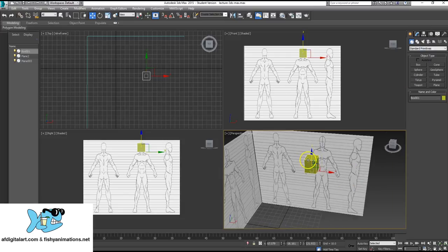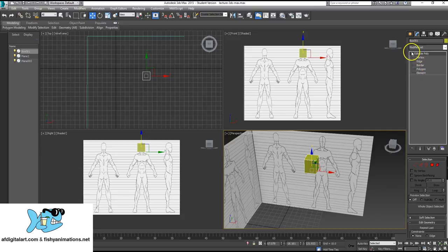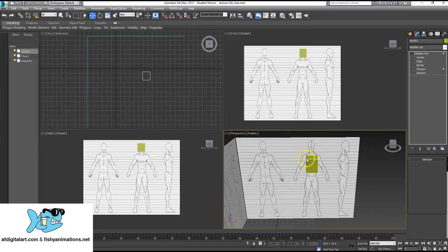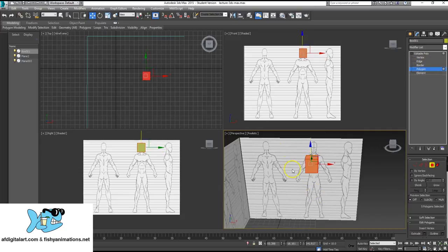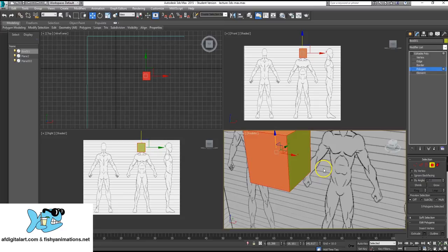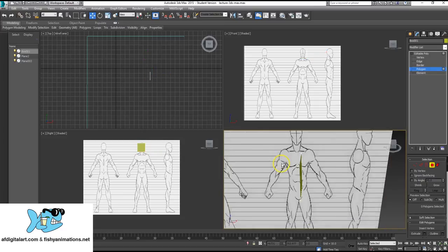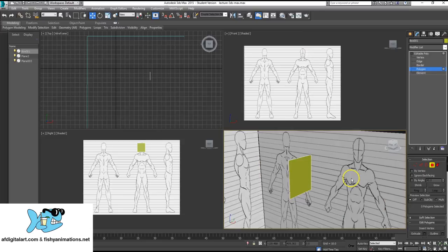I'm going to go and convert this to a polygon now. All right, go ahead and open up and go to Poly. I'll left-click and drag and select the polygons I really don't need. So we actually come down to just the simple side of this box. I hit delete. So we only have one face or one poly to really work with.